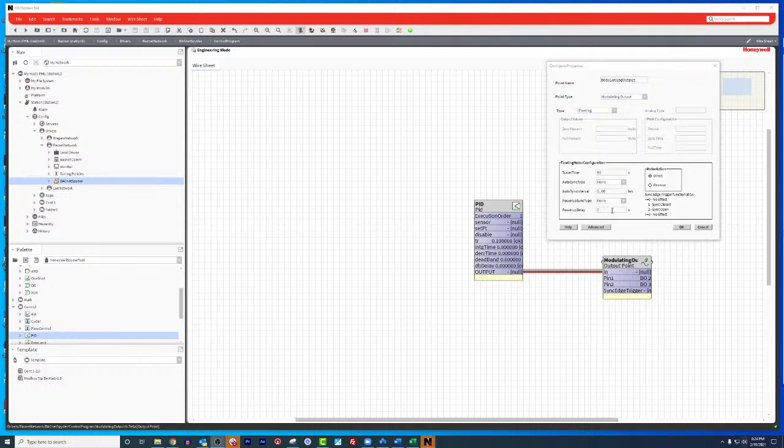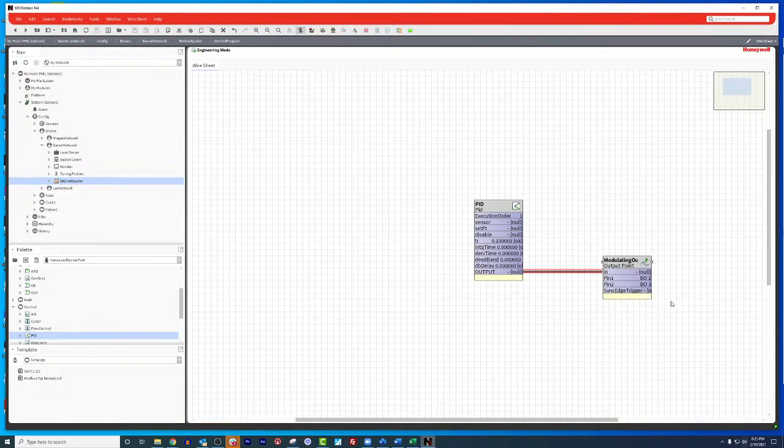But yeah, you can see kind of right here the auto sync type. I could say I sync it to closed or I sync it to open, and I can say how often I do auto sync, like the auto sync interval, and I can say what I want it to sync to when it powers up. This is not necessarily true for every controller. This is just a Honeywell Spider controller I'm looking at. Not everything has auto sync built into it. Some actually require you to go and run a sync yourself. You can kind of see it right here, sync edge trigger. So on the output itself, you would connect to that, and maybe every time it switches state from occupancy to unoccupancy or unoccupancy to occupancy, you then go and trigger that sync. So there's a variety of different ways you can do this for different controls.